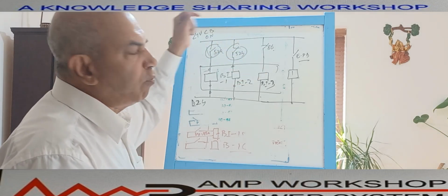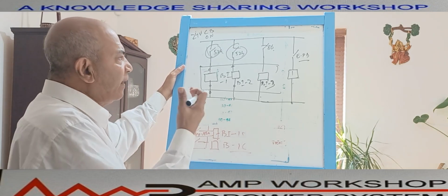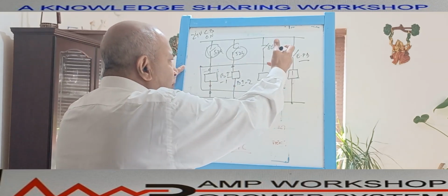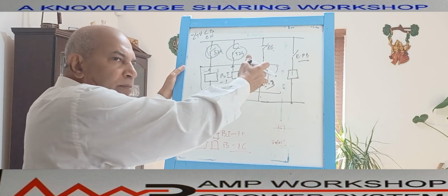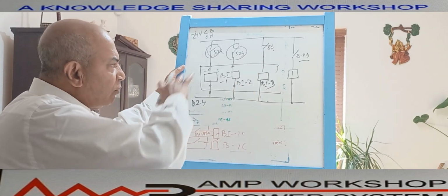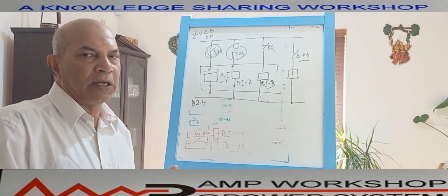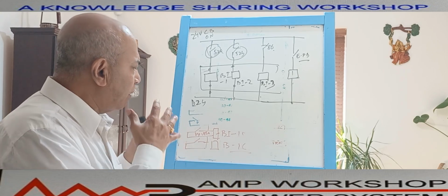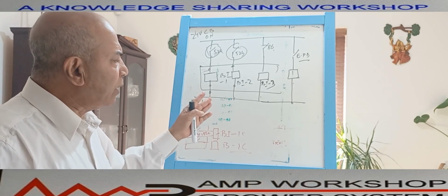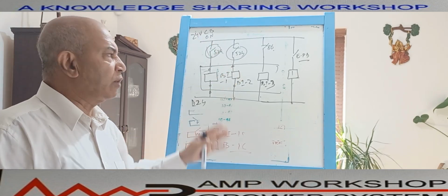In this way, whatever input you want to configure in the relay, and if that input is available in the field, you can bring it through the contact, through the wiring in the switchgear terminal block. From the terminal block, you can wire up to the relay. This way, various inputs we can use in the protection relay to configure the relay. And similarly, the protection function analog signals we can also interface. So these are the analog input and digital or binary input interface with the switchgear.